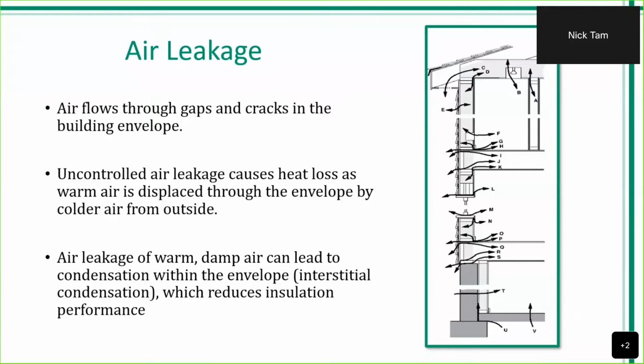We also have to take into account that when you get a lot of air leakage, we are potentially moving that dew point that we mentioned earlier from the outside to the interior side, where we can start seeing condensation. With condensation, we can get potential rot of any wood, we can get corrosion of any used metal or any type of steel, and it becomes a structural integrity issue at that point.